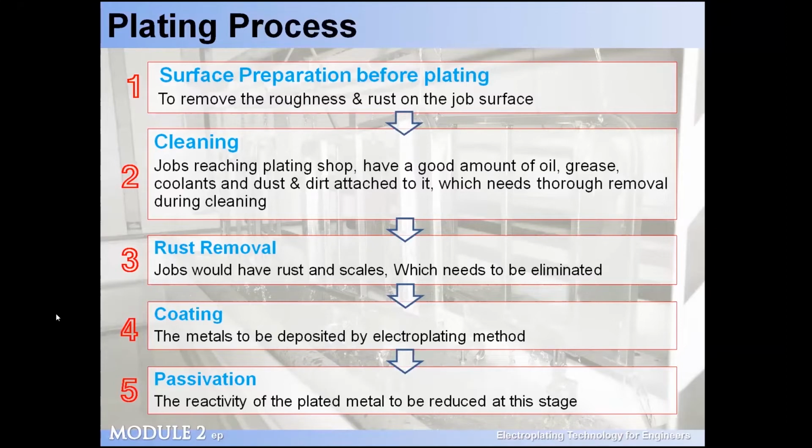Then we have cleaning. Jobs reaching the plating shop have a good amount of oil, grease, coolants, dust, dirt, etc. attached to it, which needs thorough removal during cleaning. So that is what you can say as degreasing and cleaning.